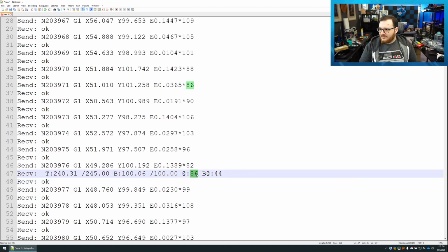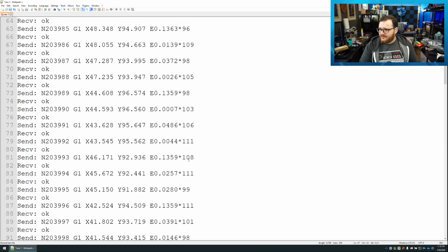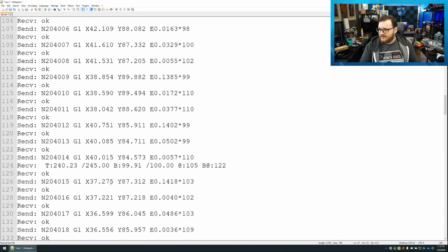So you can see here the Hotend was being commanded to heat, and one of the things affecting this machine is that I updated the firmware, forgot to do a PID tune, and in addition to that, at some point the silicone sock was removed from this printer. If I scroll down, we can look for another temp line, because it'll report every 2 seconds. You can see the bed's still within target. This is still not within the 245C temp range, and you want to see your Hotend within 2C, so this is still out of range.